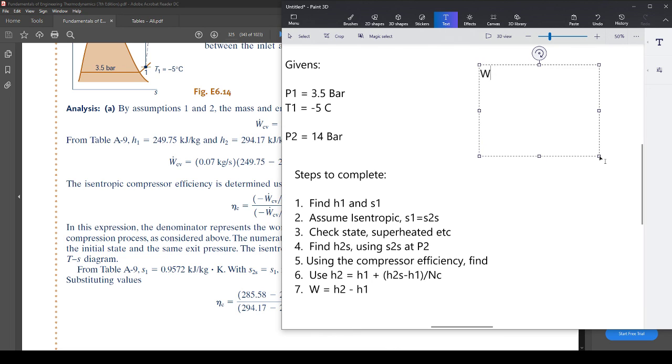I think it's this. So let's say the pump is between states 1 and 2. So you would do H2 minus H1, which is the work of the pump, but it's also equal to V times the change in pressure. Because remember, this is essentially the work of a pump, right? It is the change in pressure times the volume, right? And then you would say P2 minus P1. And so what this is called is the perfect pump equation. So this is for an isentropic pump right here.